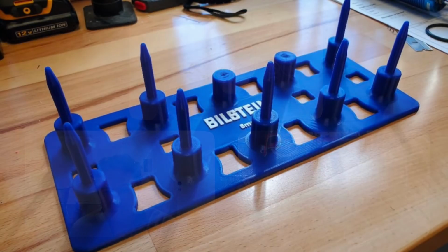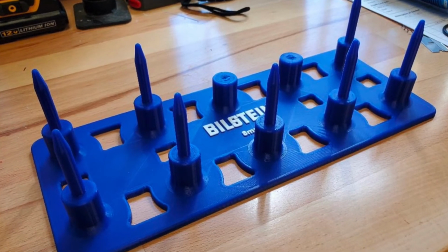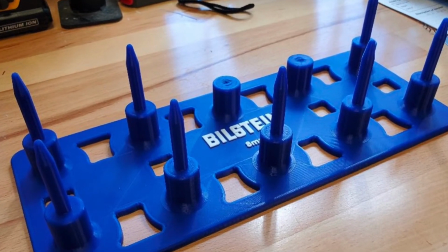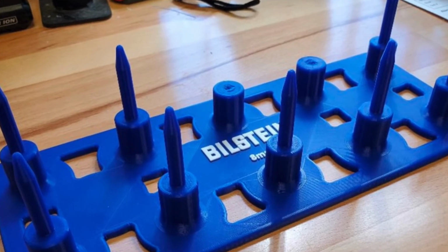Big time. That's super interesting, because before, when I would increase my infill in Cura, it did it throughout the whole part. Down at the base of this part, I had it at 35 or 40% infill, and it did the whole thing at that. But the base doesn't need that. The base can be 10 because there's no stress on that part. So by decreasing what the base was and just modifying it where it needs to be modified, it took a bunch of time out of the part.